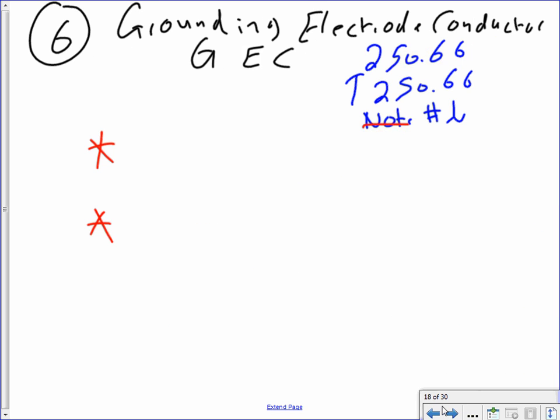Everybody knows that these numbers correlate to the diagram that you have at the beginning too, right? The same calculation, guys, applies to the grounding electrode conductor. 4 times 600 kcmil equals 2400 kcmil. For this one, you don't have to do anything else.